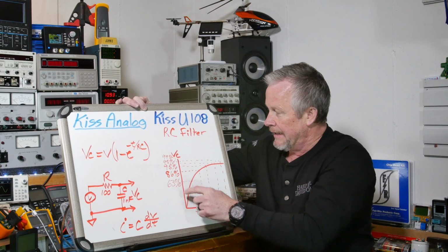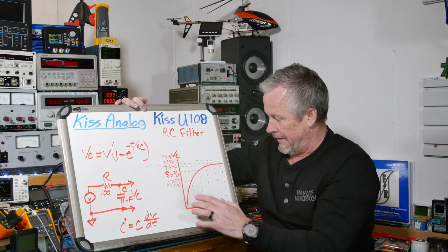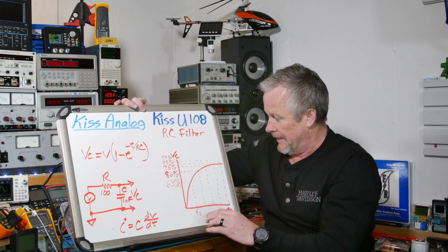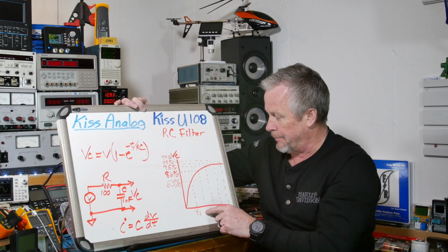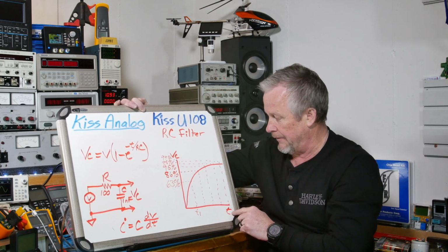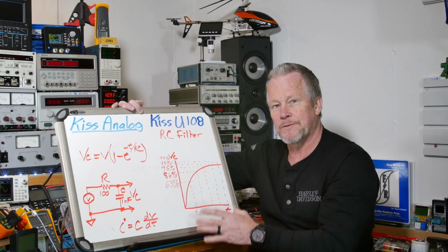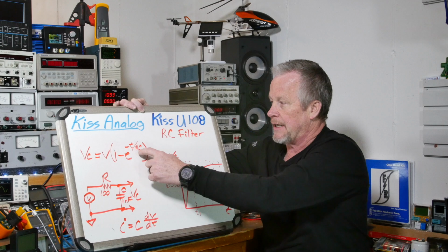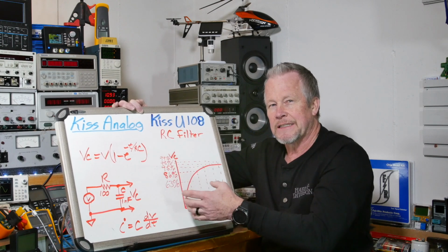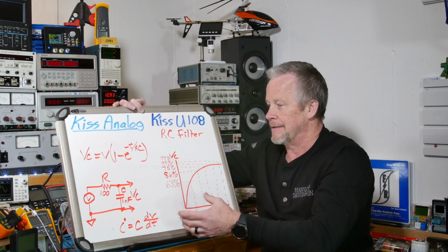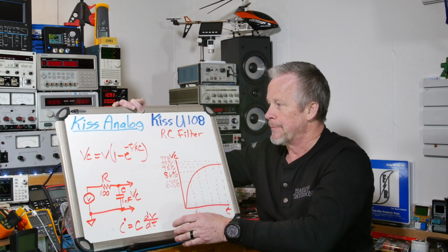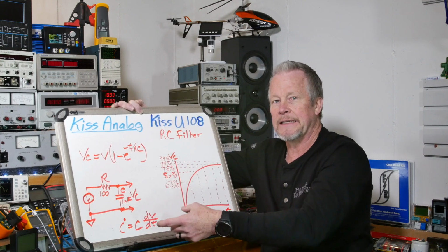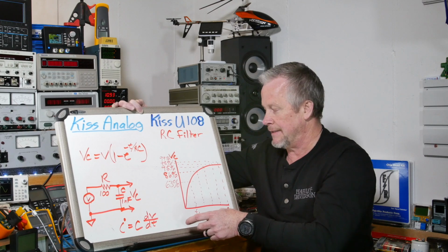You can see what I've got here. Let me explain this. I got T1 here. I meant to put T2, T3, T4, and T5. Okay, the first 5 time constants. And what a time constant is, it's just the RC value. RC is the constant because it's the constant in your circuit. And so whatever R times C is, that's your time constant.